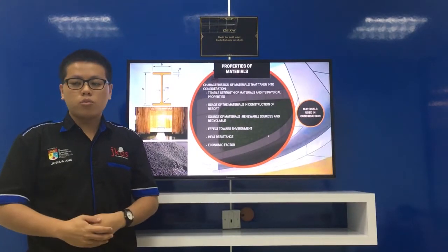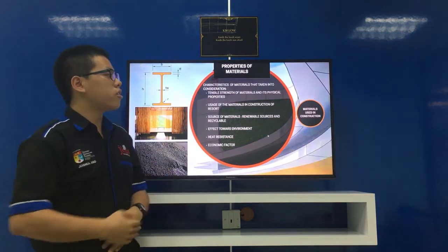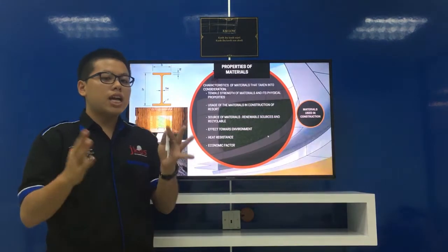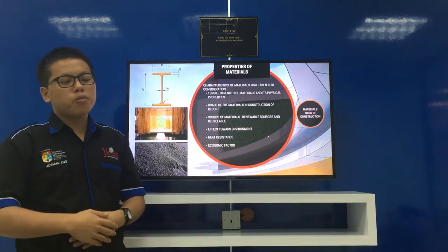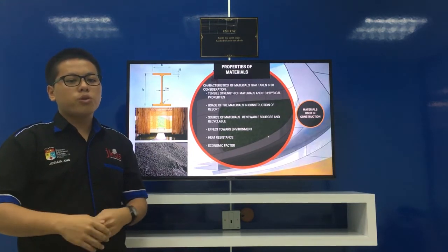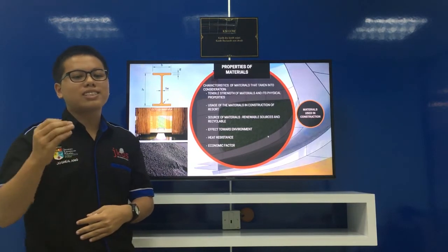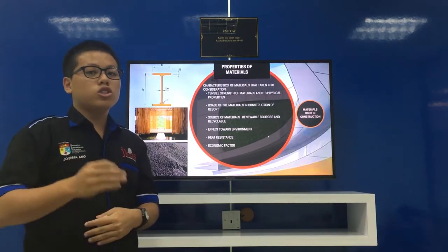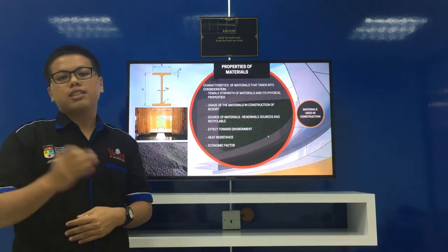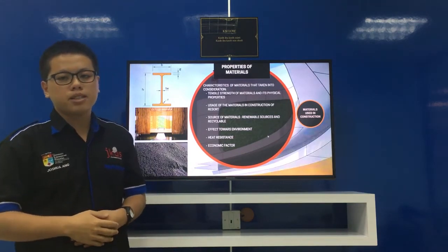Okay, now I'd like to go into more detail about the mechanical properties of the materials used for the construction of this resort. For the construction of the chalet, we are using bamboo and timber, where the compressive strength of bamboo is in the range of 40 to 80 megapascal, whereas bending strength is 50 to 150 megapascal, with a modulus of elasticity of 23.3 gigapascal, which is 11.63% of A36 steel, and with a tensile strength of 180 megapascal.